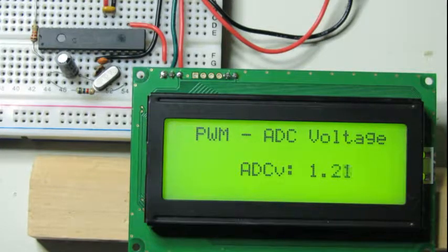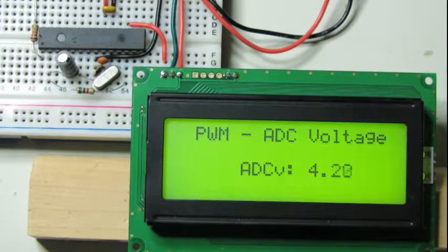If we ever get to really doing ADC measurements for accuracy, we'll go over more of the parameters that are required to read a stable voltage. Using the external voltage reference for the ADC will help a lot. And in this case, you can get a 4 volt reference and make it evenly divisible by your divisor 1024, and the math is a lot easier and a lot more accurate.